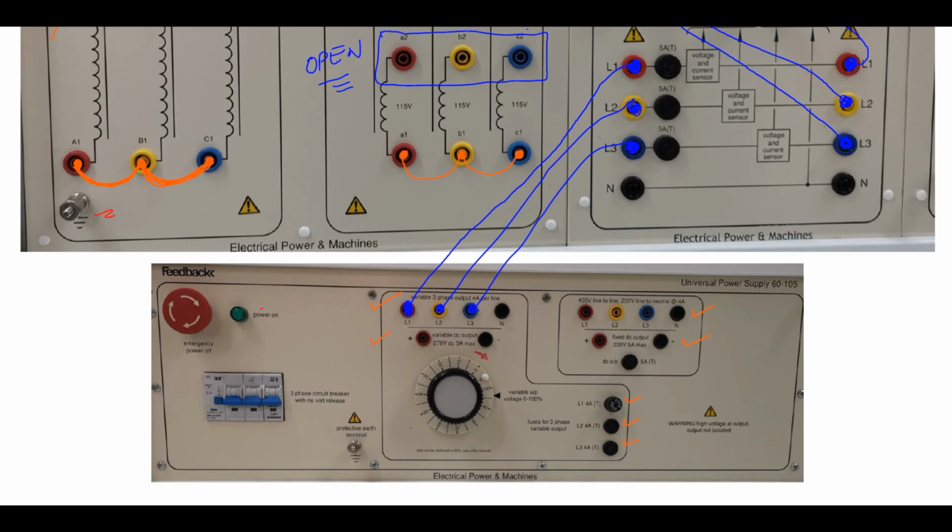Okay, this knob should be turned back to 0. Okay, and switch off your power. So this is towards 0 volt, this position like that. After that, you make a short circuit in the secondary side. Those windings are separated, and we can connect them through 2 wires here. By doing this, we are doing our short circuit test.